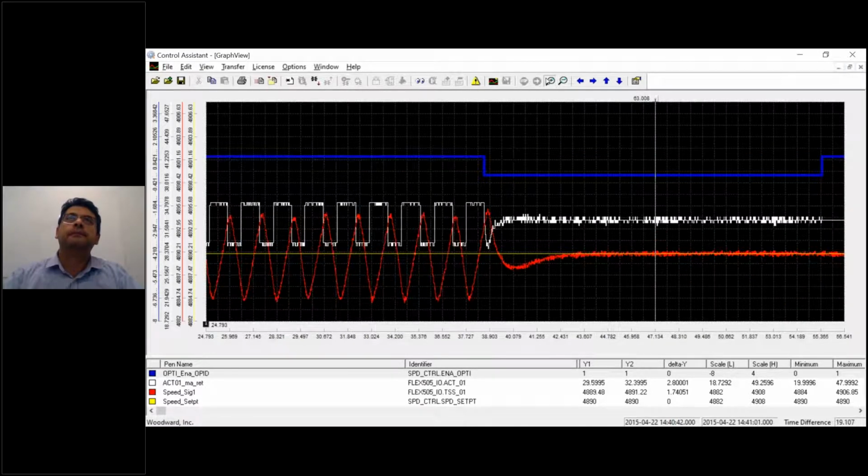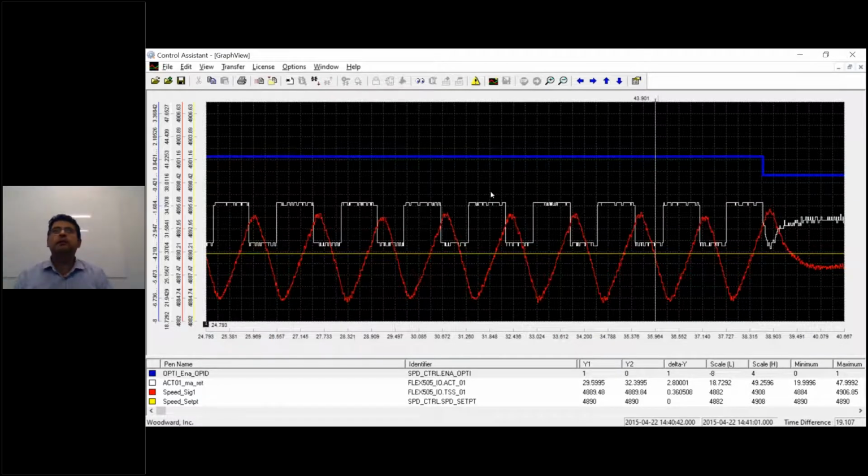The moment we enable adaptive PID tuning in our controllers, we do step changes in the actuator. We open the valve and close the valve, open the valve and close the valve in cycles. And the controller calculates the response time from opening the valve until we start to see changes in the speed. We use a combination of the Ziegler-Nichols method, the one that we discussed earlier, and the Cohen-Coon method, so that we can achieve what we call an opti-tune controller or opti-tune response.